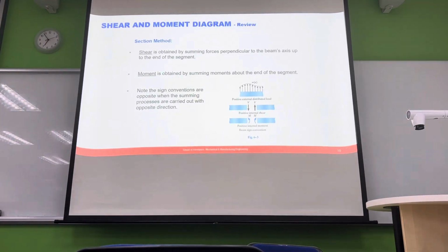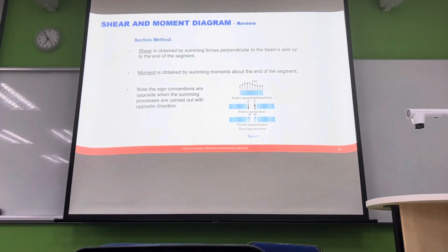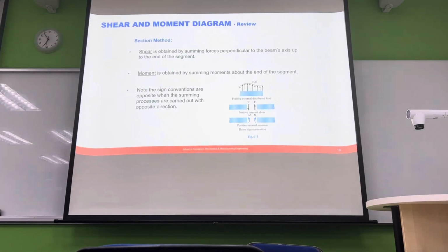Stresses are just forces over area. So when you think about stress, you should also think about it as a local force in a very small area. So when we apply some sort of loading W, and look inside of that object, that is going to generate some internal shear stresses and some internal bending moments.